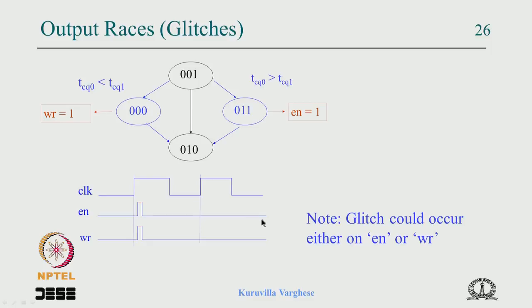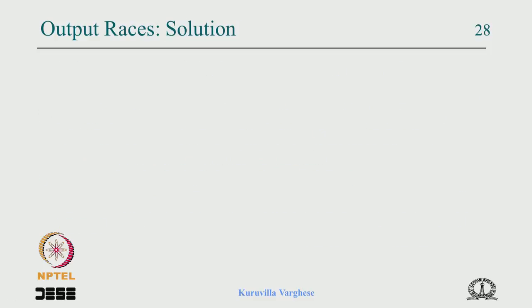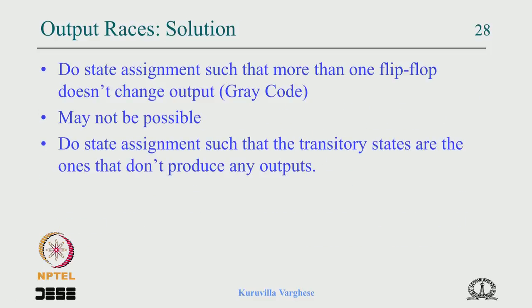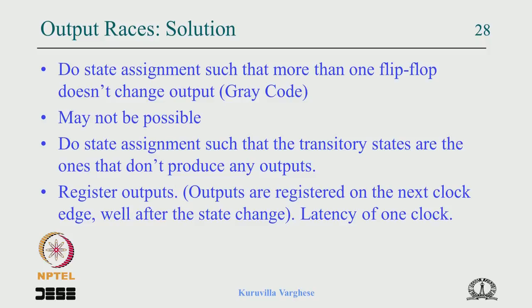So why don't we put one flip flop at the output logic and give a clock to it, so that a valid output is registered and we get a registered output. This glitch won't be registered because it appears briefly, for a short duration. That's the most permanent solution.